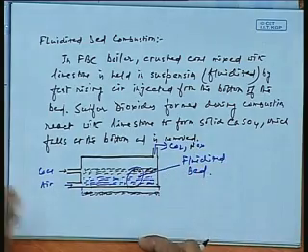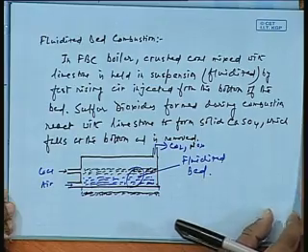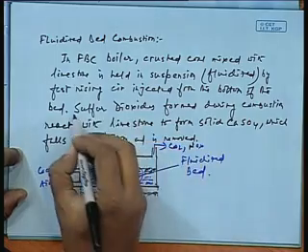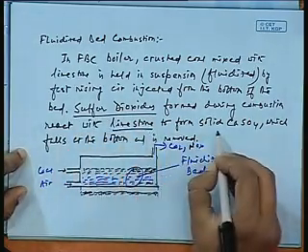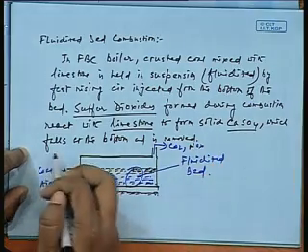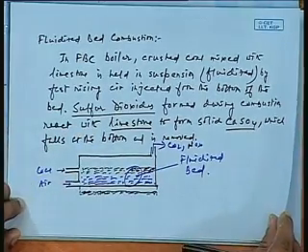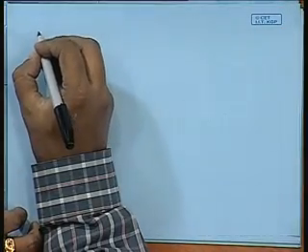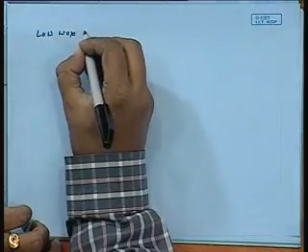So, as you can see, this is conceptually a fluidized bed. This is good enough just to say how, as we know, sulfur dioxide is removed. We generally make sulfur dioxide react with limestone to form solid calcium sulfate, which falls at the bottom and is removed. So, this is one way of reducing sulfur dioxide from the flue gas. Another is low NOx. One important thing about low NOx combustion.